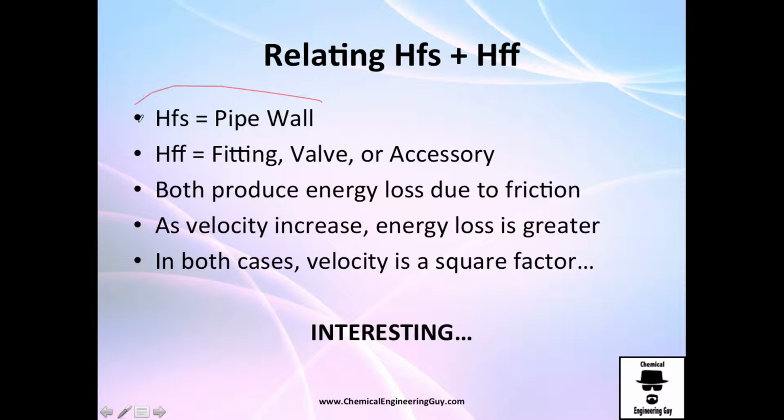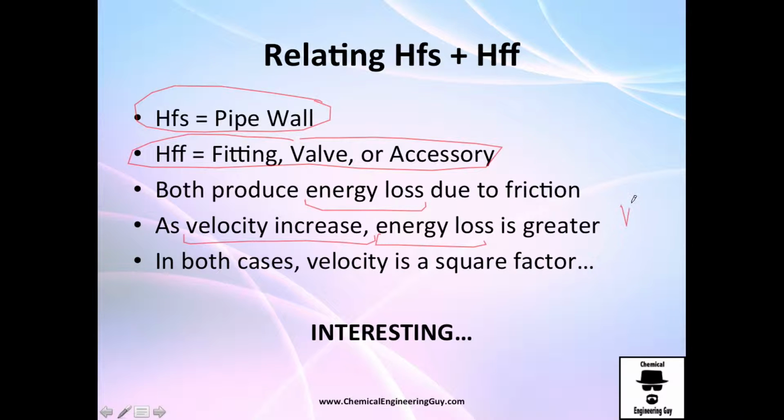So what we want to do is, essentially, we have the pipe wall friction, and we have the fitting, valve or accessory friction. We want to relate those energy losses, and in both cases, as velocity increases, the energy loss is greater, and actually we have this velocity head. So that's what we have in common.